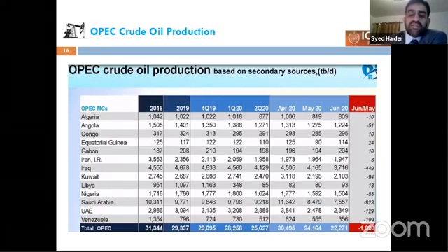Then comes the gasoline part that we use for our passenger vehicles. Then the third part, as the temperature goes up and up, is naphtha, where you can see all these plastic chemicals made from petrochemical products. That's the grade of oil that's used, called naphtha. Then at the higher temperature, 160 to 230 degrees Celsius, it's kerosene, the jet fuel that the whole aviation industry uses. It's further boiled from 230 to 425, and the diesel and heating oil come in.